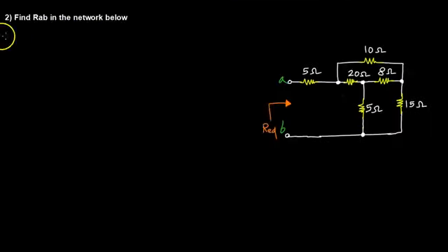That summarizes this problem. Okay, so for this problem we also have multiple options for simplifying, and the issue is this 10 ohm resistor, because if it wasn't there we could simply combine the 15 and the 8 in series. We could then take it in parallel with 5, then combine that with the 20 in series, and finally add the 5 ohm in series, and that would have been done. But because of the 10 ohm resistor, we have to somehow relate the 3 resistor combinations with this 10 ohm. So the only one we can do right now is the one involving all 3 of these resistors.